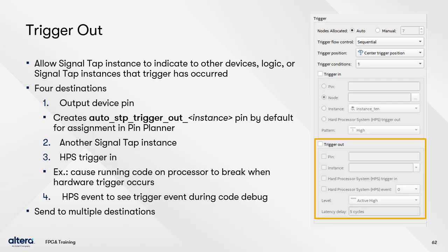The latency delay field at the bottom of the trigger out section indicates how many clock cycles are required before signals coming into the logic analyzer instance generate the trigger out signal. This value, calculated automatically as the logic analyzer is configured, includes all delays to the signal tapped instance.